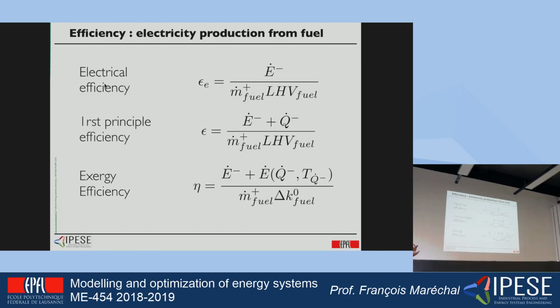In order to be able to sum the electricity and the heat in a smarter way, what you can do is to transform the value of the heat into its exergy value, which means that the exergy of the electricity and the exergy of the heat are, let's say, measuring the same thing.